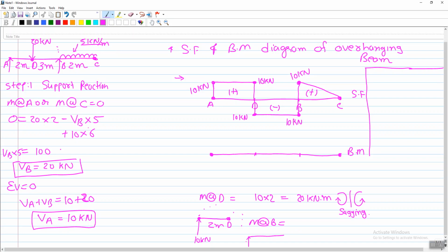So the moment at point B is easy to calculate from the RHS only, right? Here this is B. On the RHS, you can say it is 5 kilonewton per meter in magnitude. UDL is acting over a span of 2 meters, right? So the total moment is like the previous case, 10 into 1, from the RHS, clockwise.